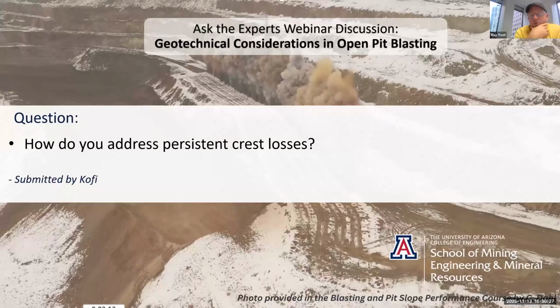And then the shovel operators would come in and they had this cultural value around digging to hard. So they would just keep advancing the dig until they got to hard rock. Didn't matter where the crest was. So it was this combination of a lot of different factors that they were really not doing at all well with design conformance because of all of these interrelated factors. So it's actually kind of a tough question. There's a lot of things that have to go into this one, because you can approach it from design conformance, energy dispersal, bench face angle, cultural values around safety, quote unquote. There's a lot of pieces to this.